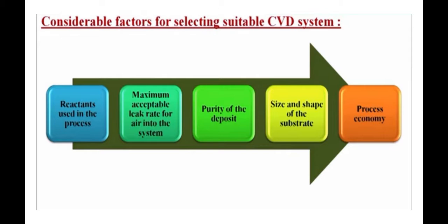That means whether the whole process is expensive or maybe it is cheap, and not only that, what type of substrate material you are going to use, and whether the reaction between your reactive gases and substrate material can be done or not, and what conditions inside the chamber you require, whether you need more pressure or less pressure, then what energy source you are going to use. So depending upon all these things you have to choose the better CVD mechanism for your particular substrate.